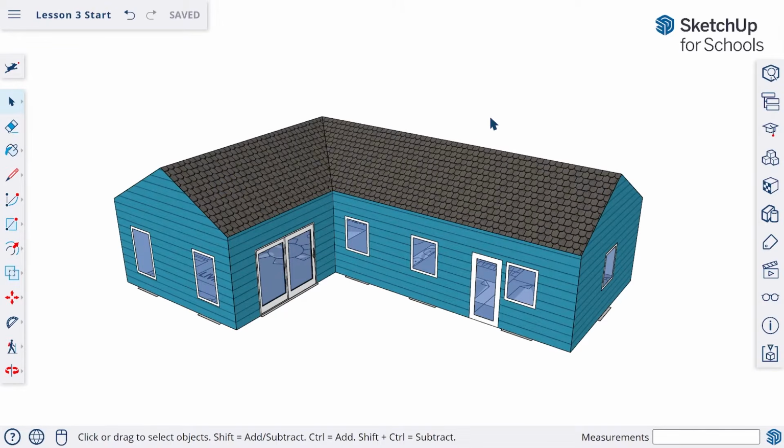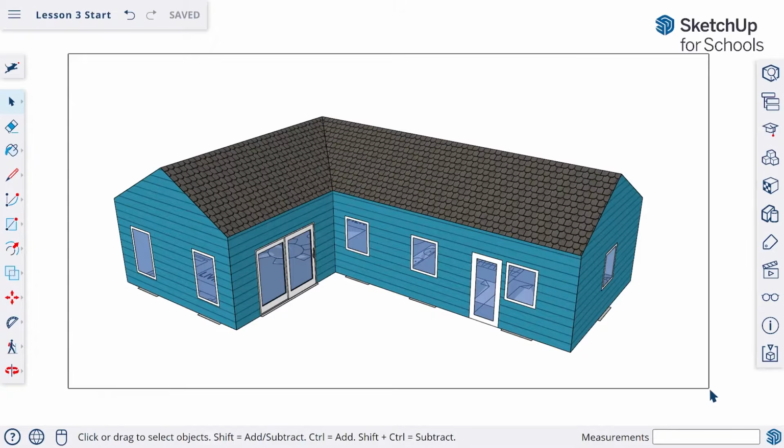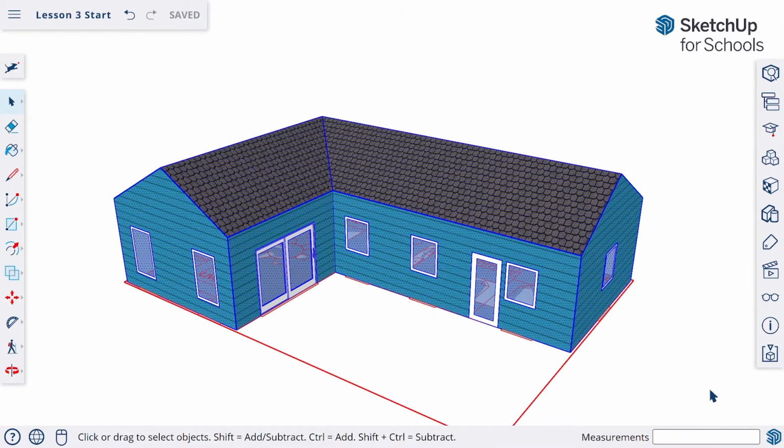The first thing we can do is simply make a copy of the existing model. This way, if we make any errors in rotating or flattening the file, we always have the original to come back to. With the Select tool, drag a window around the entire model to pre-select all the geometry. It's okay that the floor plan is selected below from Part 2, because this is locked, it will not copy when we move it over.